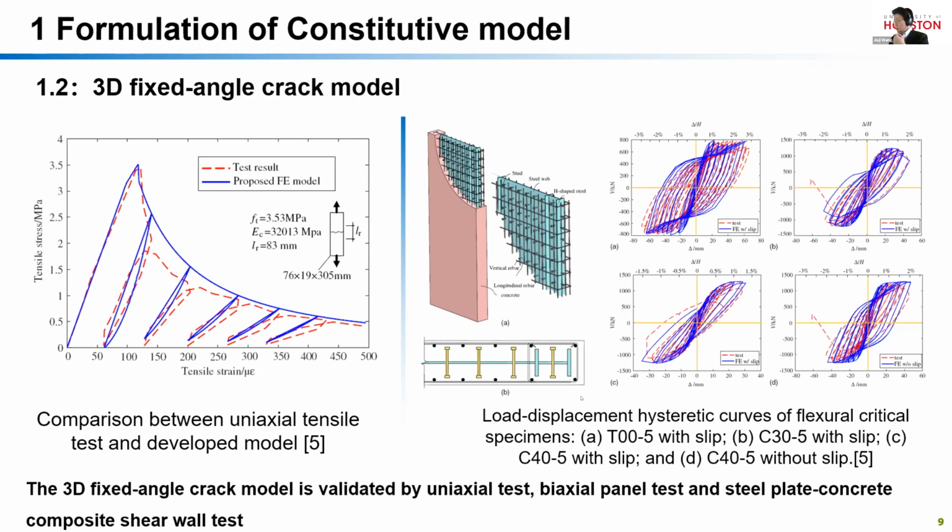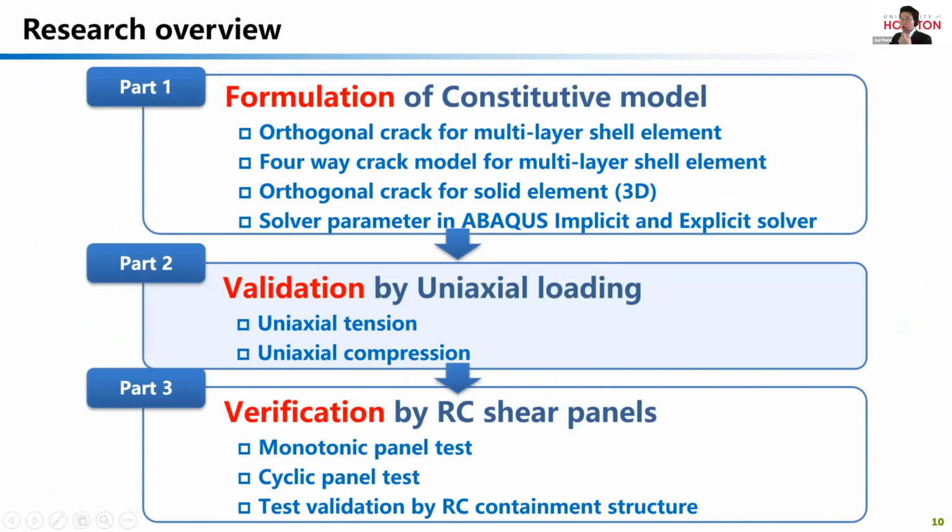For the composite shear walls, a large amount of composite shear walls are simulated using these three-dimensional solid elements and the developed models, and the influence of interface slip on the simulation result is investigated. Subsequently, the developed two-dimensional model is validated by uniaxial loading.